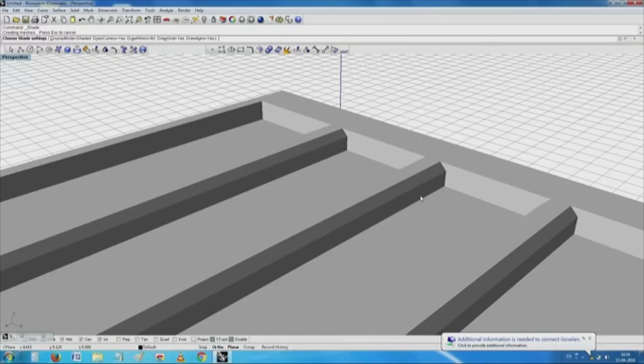The bottom first layer was the base. Probably it could be made out of, depending on the thickness, suppose it is a 1 mm thickness and the resolution is around 0.2 mm, usually they will have 5 to 6 runs on that to build up that 1 mm, and then later on they will build the ribs. Starting from the ribs onwards, the algorithm which is used for moving it, algorithm in a very general and abstract way, the path which the nozzle takes will be different.